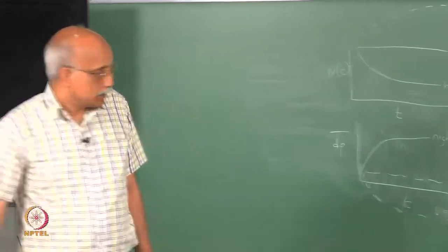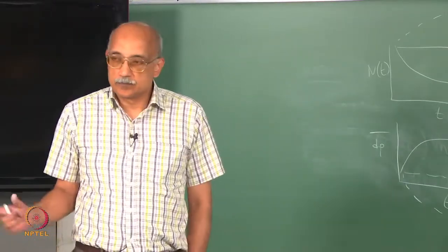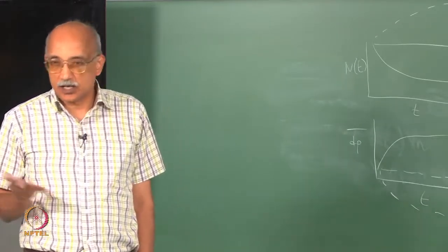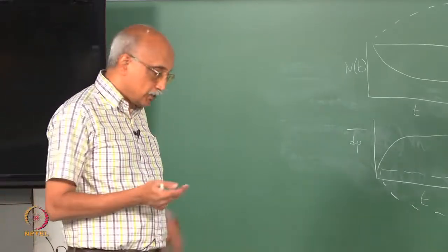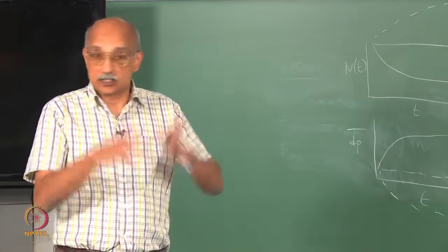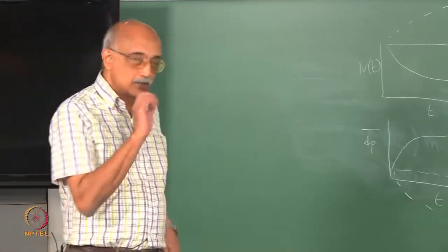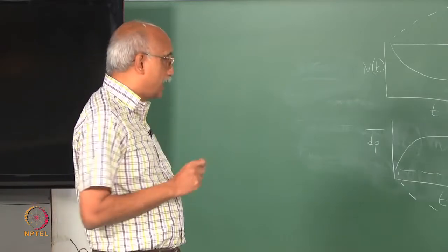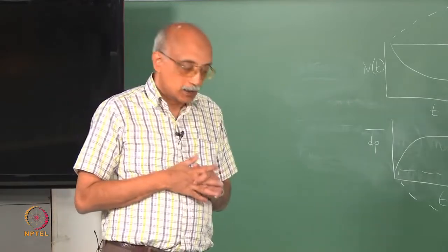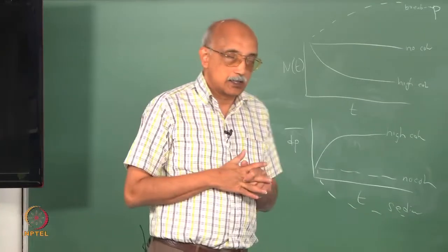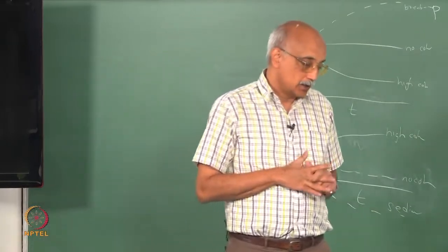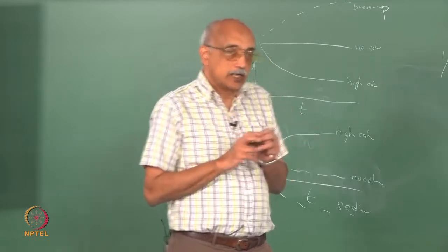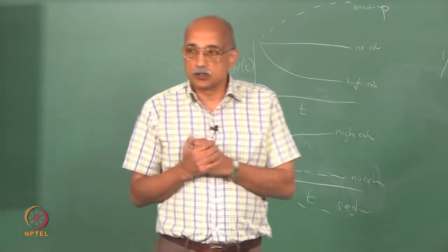But as you can imagine, as particles get finer and start approaching nano dimensions and so on, this assumption can break down. And also, even though this assumption may be accurate for the system as a whole, there may be isolated locations in your system where the assumption breaks down. Then what happens is something called slip. Slip happens when the continuum assumption breaks down, and at local neighborhoods molecules, or particles, start to behave like they are in the free molecular regime.